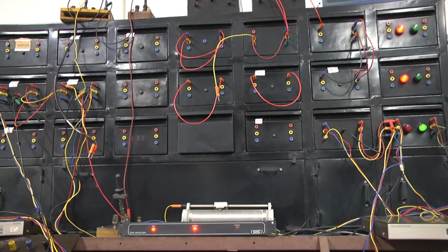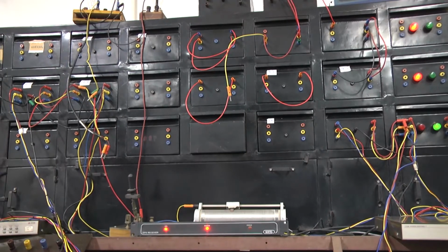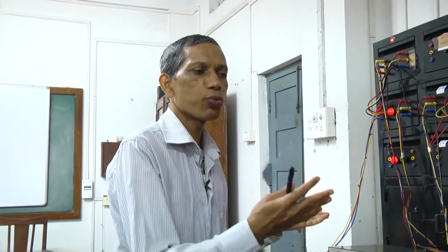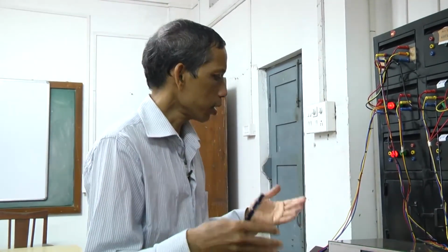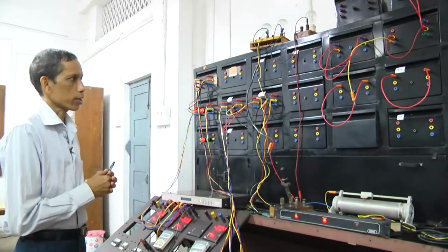By that way, the angle of the generator with respect to the grid side goes on changing; more power input to the grid from this alternator increases the delta angle between the two buses. That is reflected by these two PMUs, which will be shown in the demonstrations through the PDC after the synchronization part.